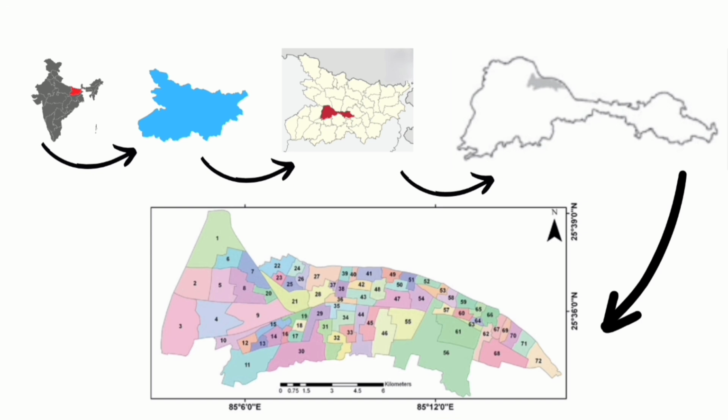This is done for better administration and other things. So you should get a map of this subdivision. This in India is called wards. You should get a ready-made map of these ward boundaries. And if you don't have a ready-made ward boundary, you can digitize it using georeferencing from a hard copy that you may have.